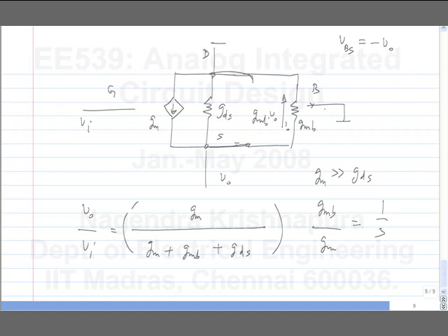Okay. So this is something you have to watch out for, and I've already said several times that in typical technologies you can connect the bulk of a PMOS transistor to its source, but not necessarily for the NMOS transistor, because all NMOS transistors share a common bulk. Okay, you can't connect each one to its own source. So when you make an NMOS source follower, typically you have this problem. If you have a PMOS source follower, you can connect the bulk to the source and get rid of this problem. Okay. So if you want a voltage follower whose gain must be 1, you have to use a PMOS transistor. Okay. So I introduced this because this is also useful in the discussion of biasing, and we have to do it at some point anyway. So we'll continue this in the next class.